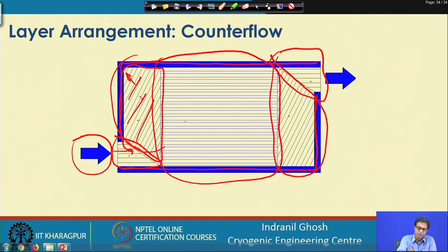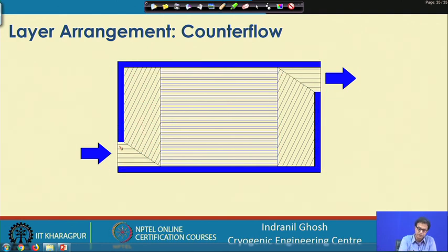So, what we need to do is select a type of fin such that this fluid will come in and will be coming out of this region to this region. So, we need to put some kind of perforated fin, so that this fluid will be flowing up to the last end of this one. And if you look carefully into this part, you will find that this is where it has the least length, and here it will find the longest path to move out.